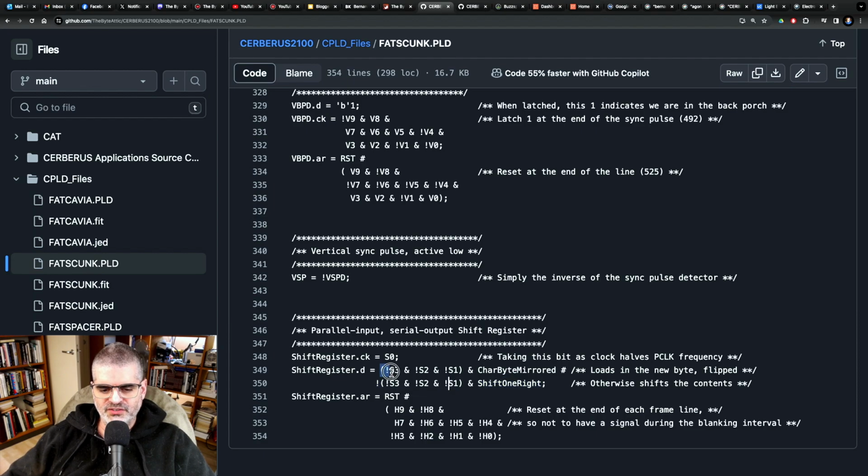And notice that I'm using the same condition on top and at the bottom, but in the bottom it's inverted. So the wiring now is such that either this will be wired to the flip-flops, or this will be wired to the flip-flops, depending on whether this condition is true or false. And this is the OR. So you could draw this as a schematic with inverters, ANDs, and ORs, and you would see that this is a form of conditional multiplexing, in which the control input of the multiplexer is this equation.